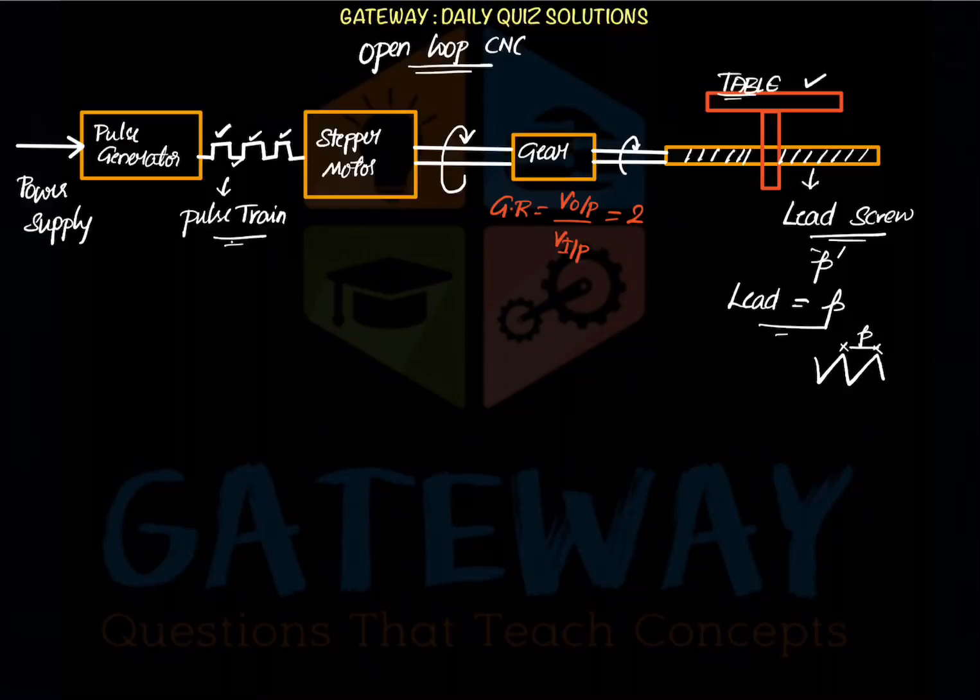If you are giving an input of, suppose the gear ratio is 2, if you are giving an input of 1 meter per second, then our output will be increased by 2. If you are giving 1 meter per second, then the output will be 2 meters per second. Suppose the gear ratio is 1/2, we will take one more example of reduction.